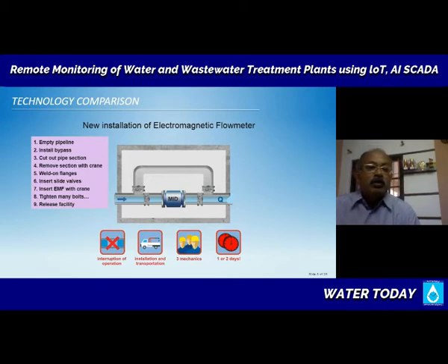Then what happens when you reduce the pipe diameter? You get a pressure drop across that. Not only for a day or two, but for the life of the system, we have created a restriction and a pressure drop by reducing the pipe diameter. Now you have technology available which ensures that you don't have to do such things. You can have a full bore pipe, you can just go on doing your piping and then come and fit your metering later. These are the things to bear in mind when you think of putting up measurement devices.